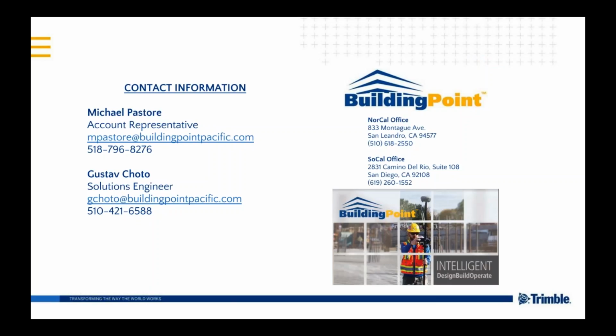A couple questions did come up. One being, what 3D formats can you bring into Vico Office when we're comparing models? I think we answered this a little earlier in the demo, but as I mentioned, Vico Office is pretty agnostic. So we can bring in Revit, SketchUp, Tekla, ArchiCAD. Am I missing any there, Gustav? Yeah, Bentley, CAD Duct, and any file type that we don't natively support, we could still bring it in. We would just need to export it as an IFC file.